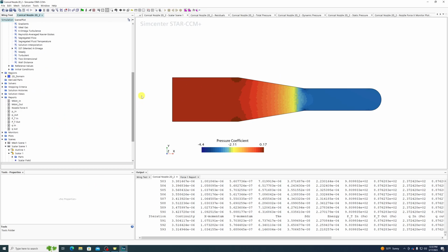Now, if we want to measure values at the inlet, at the outlet, or along the walls, that's fine. But how the bloody hell do we measure the pressure here? Right here. Or right here. Or right here. Well, you need somewhere to measure the pressure, is kind of the problem. You need a surface that defines where you want to make the measurement. We don't have a surface where we want the measurement.